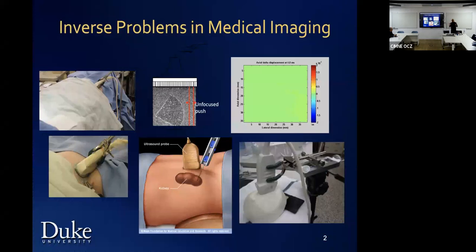Before I go on, let me clarify something. You're going to hear shear modulus a lot in the presentation. What happened with the bulk modulus? We're going to talk about isotropic elasticity. What happens is soft tissue is like water, right? So nearly incompressible. The bulk modulus, I know what it is. Or for us in wave propagation, what is the speed of sound in water? 1,500 meters per second. That's known. I treat it as known always. What is not known is the shear.